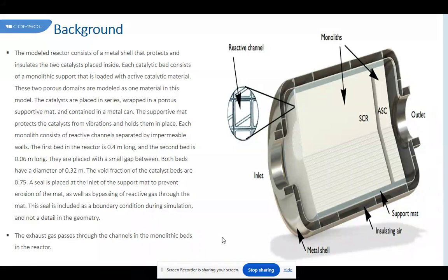Although this change is small, together with the inlet velocity, it led to a channel apparent velocity in the 400 per 6.5 monolith almost twice higher than that in the 900 per 6.5 monolith. Such a combination of factors is quite consistent with the result here in the simulation, and this simulation shows the reaction rate for the four combinations of ring and core monoliths where both had the same volume. The profiles are consistent with the results in the simulation.